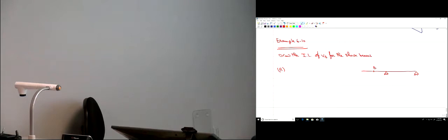That way you just need one figure for the bending moment, one figure for the shear force diagram, one figure for the normal force diagram. It's the envelope of the normal force diagram and the shear force diagram. If you're going to do it for the entire frame, okay, you just have to label; I need to see the values on the drawing. If you don't want to label by hand, then you plot for each beam, and you have to label your beam so that I can understand which beam this is.